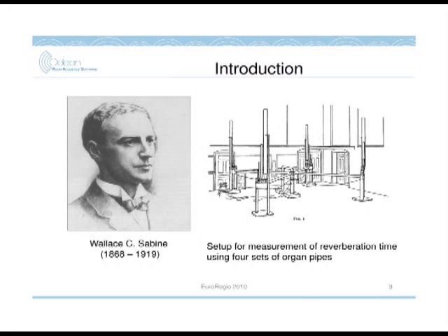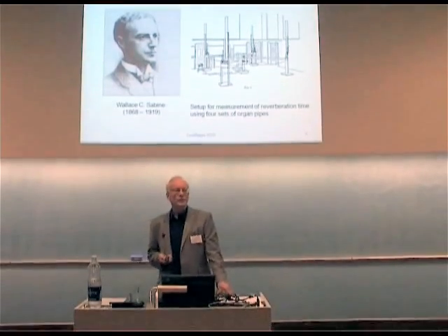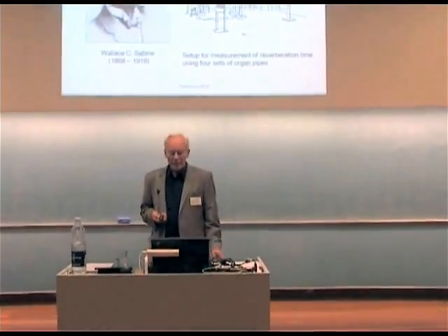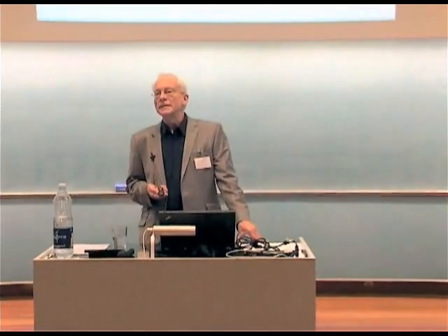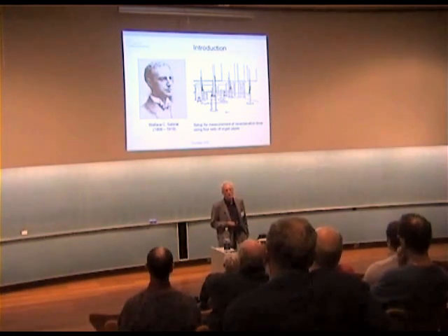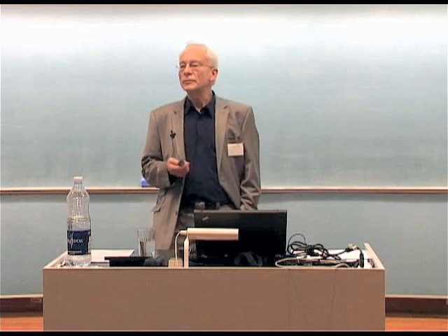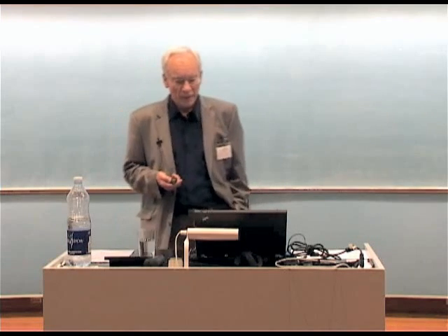But we start with Wallace Sabine, who could be said to be more or less the father of room acoustics as a science. It's more than 100 years ago now that he started to look into room acoustics and came up with the concept of reverberation time. And in those days, they didn't have the equipment we know today. So I just should like to mention how he has described in his papers the technique he used to actually measure reverberation time in rooms.